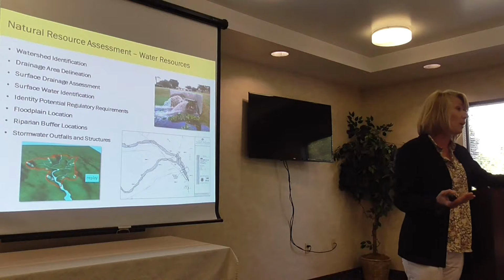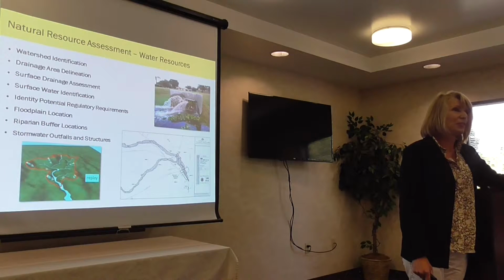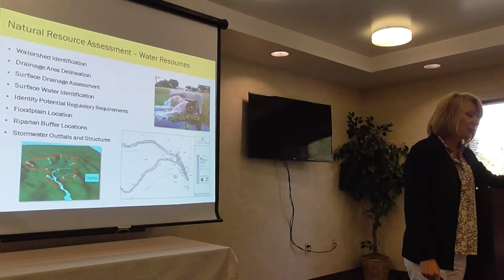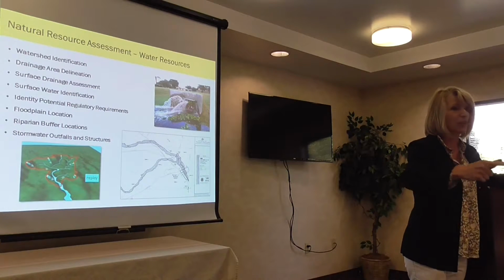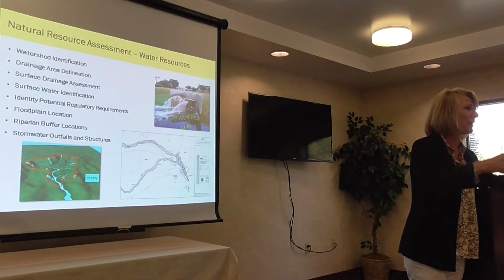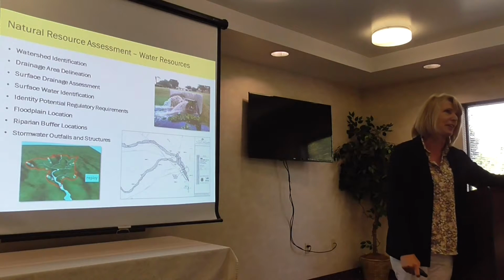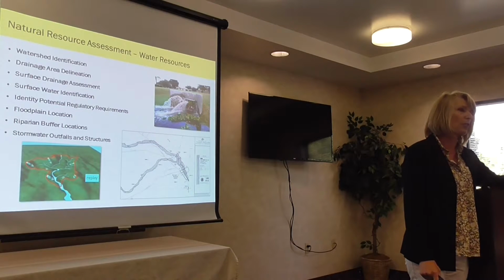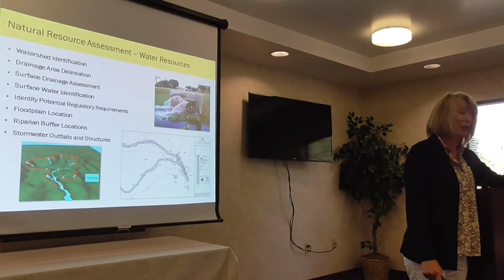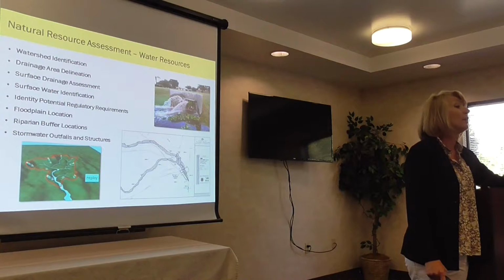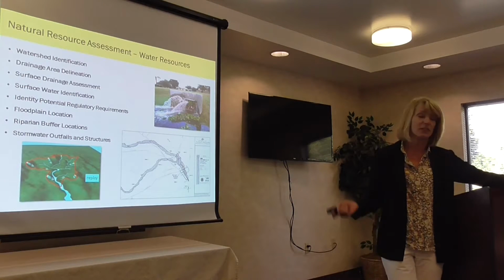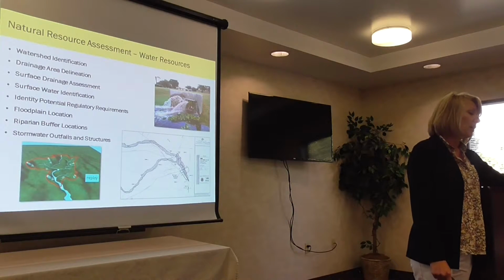Are they actually working? A lot of times, you can't see this. We'll go back and do assessments, and you're basically tracing downspouts out, trying to find where those outfalls are, or tracing back outfalls to find out where the storm sewers are, what's feeding into it. Sometimes you can't even find it. Sometimes municipalities have no clue. And in some cases with utilities and things like that, we'll talk about this a little later.